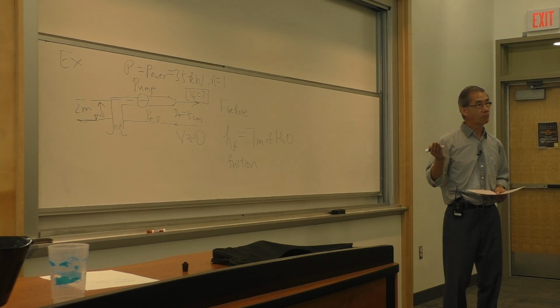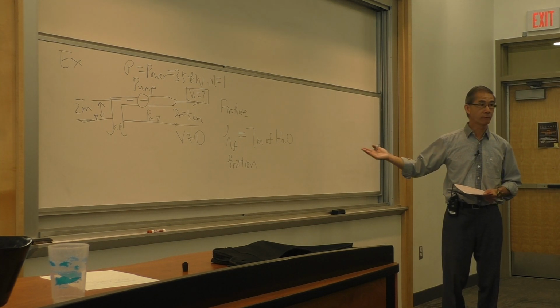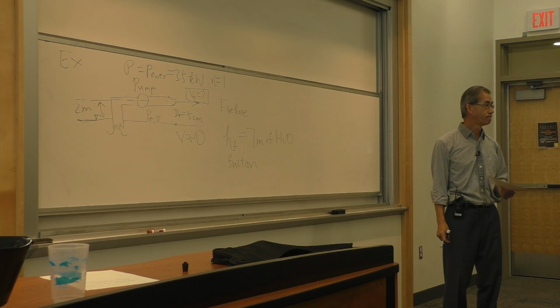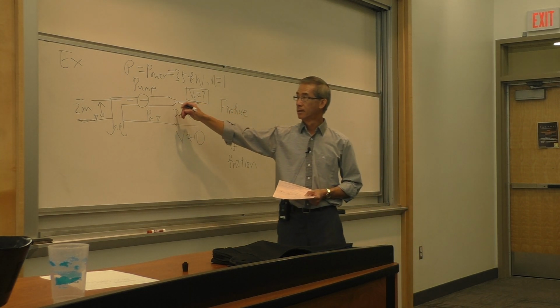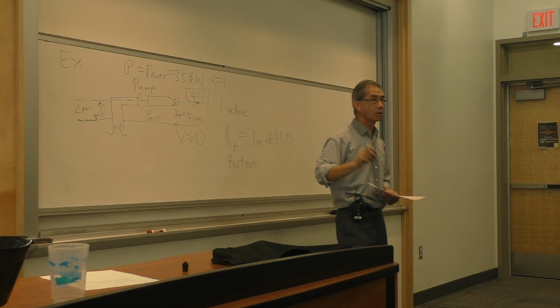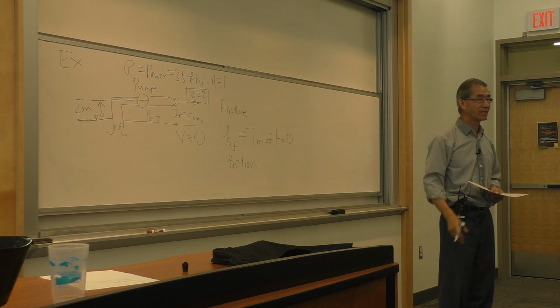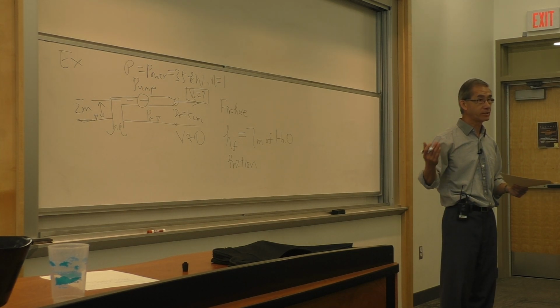So the pump work is being used to overcome elevation change of 2 meters, the friction, and what else at the end? What else? This velocity, if I make the nozzle smaller, the velocity goes up faster. What has to be provided to make the jet shoot out like a cannon? Well, the kinetic energy of the jet, right? Do you see the physics?